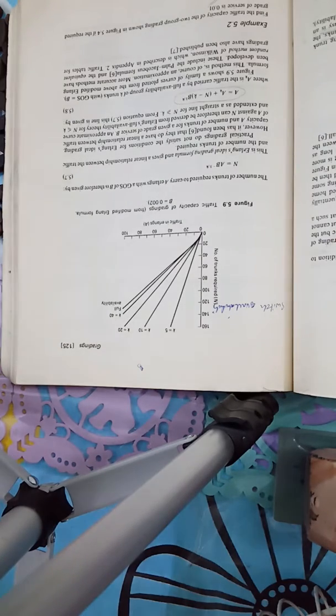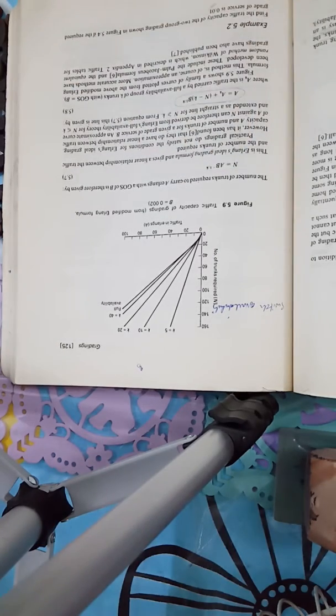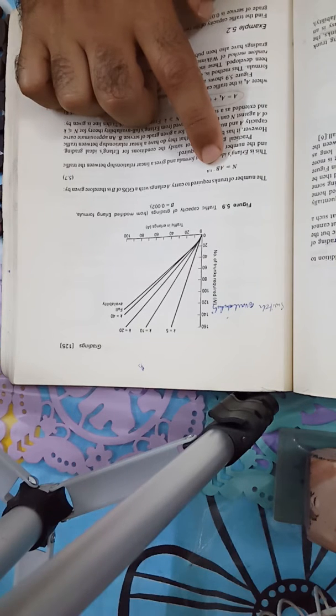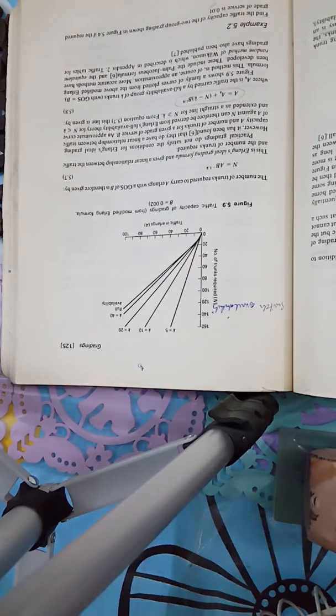This is also called Erlang's ideal grading formula and gives a linear relationship between the traffic and the number of trunks. The number of trunks is n, the traffic is A. So there is a linear relationship because B is given by the regulatory authority, which is normally given as 0.01 for the trunks. So this gives a linear relationship between n and A.